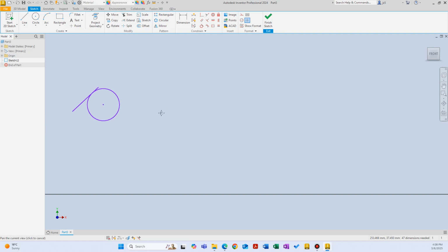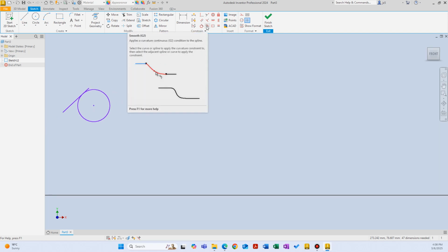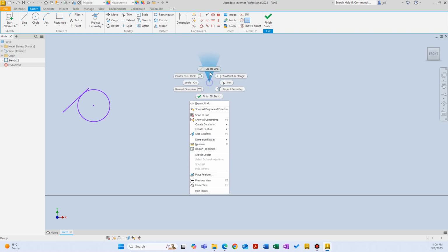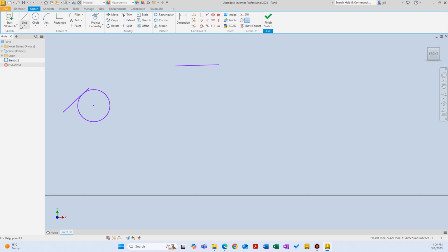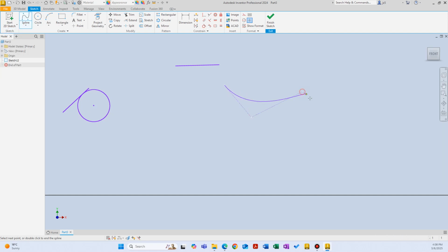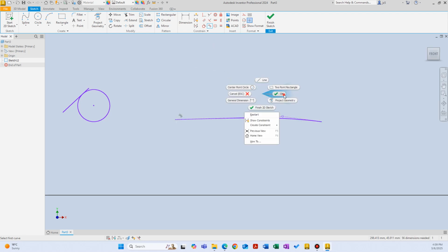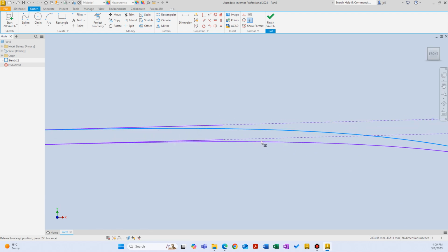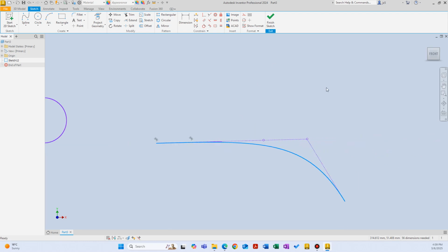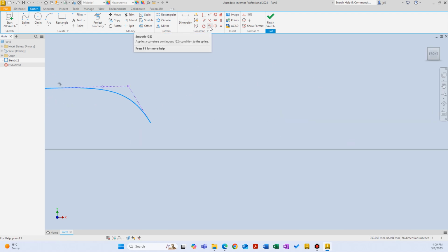And the other two constraints that we didn't look at are not very commonly used, but sometimes as you use Inventor, you start using them. One of them is the smooth constraint. So if I have a line here, and let's say I have a spline, something like this, and we're going to talk about the spline constraint too. I can use a smooth constraint with this line and this spline, and now it is constrained on this end here. See, it is constrained to that. And again, you can just keep your cursor on it. It gives you the preview of that constraint.